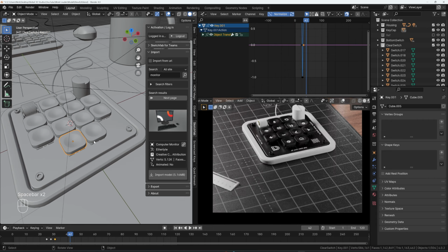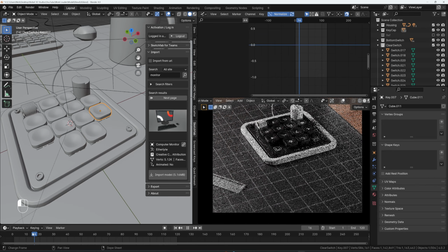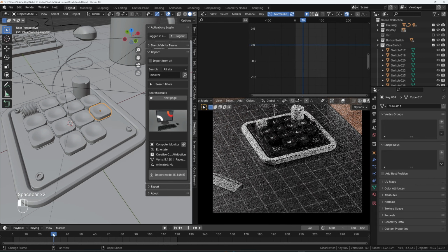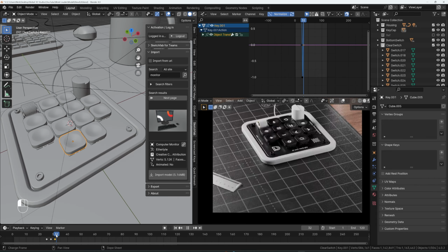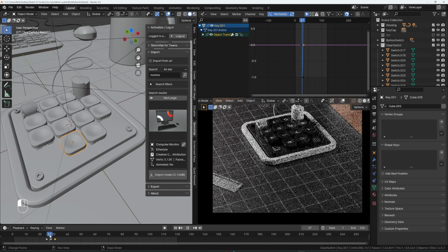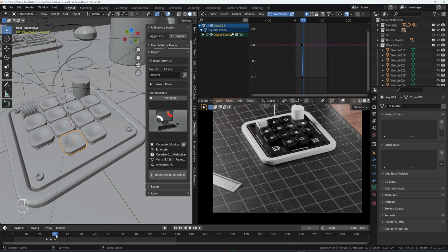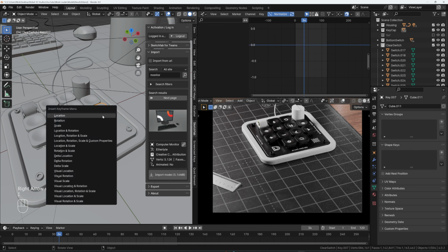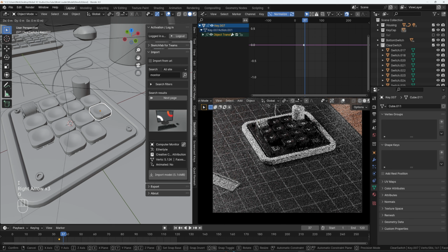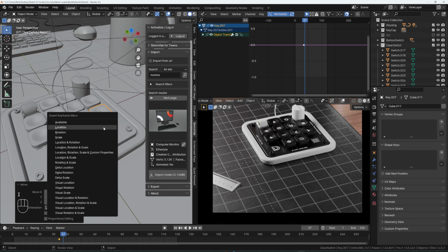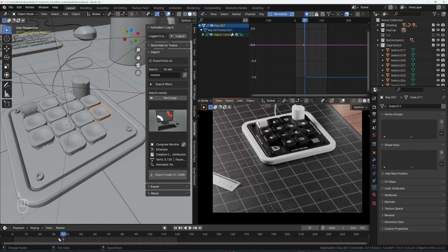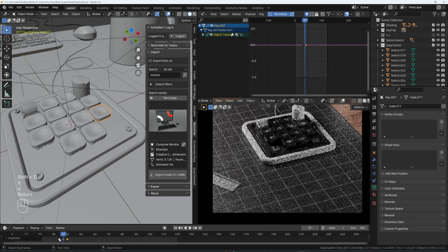So now I just kind of picked an abstract way to do this. On this one we ended on frame 31. So I'm going to give it 3 frames. So these are 3 frames a piece. So I'm going to go 3, 3, 3. Go to the last one, 1, 2, 3. I clicked it. Insert a location, 1, 2, 3, G Z. Bring it down to that first intersection. Insert another location, and then just grab this one, Shift D and X by 6.